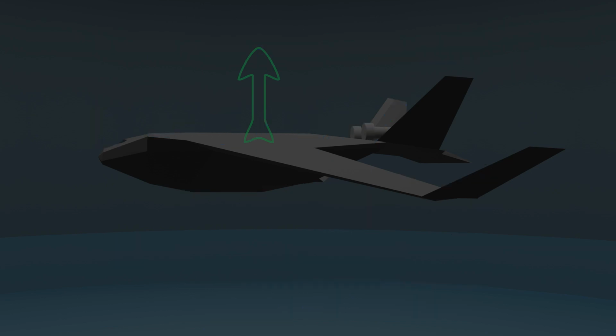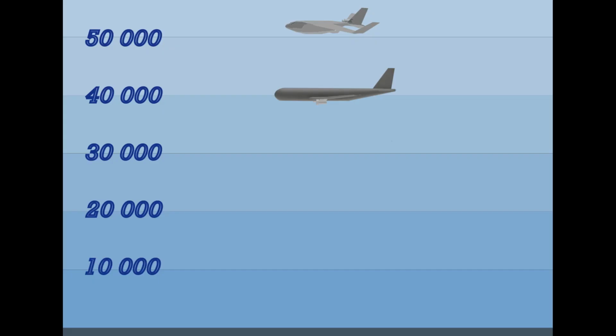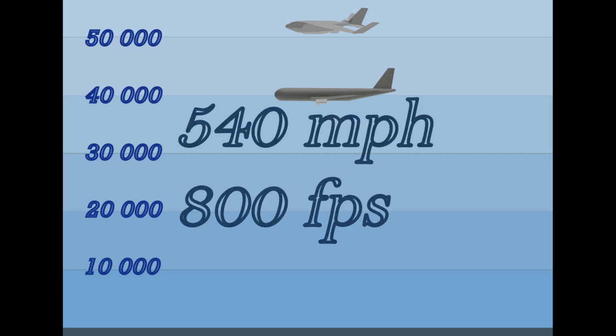the angle of attack. For a commercial aircraft, Mach 0.85 is about the highest effective Mach number. Above that, you start getting into severe compressibility effects. The speed of sound is roughly constant from 35,000 feet to 60,000 feet, which means that the speed of the aircraft is also constant. If there is a lower wing loading, then the wing loading can be balanced at that velocity, which is about 540 miles per hour, 800 feet per second, at a lower mass density of air, which means a higher altitude. That lower mass density of air means less friction and drag on the aircraft.